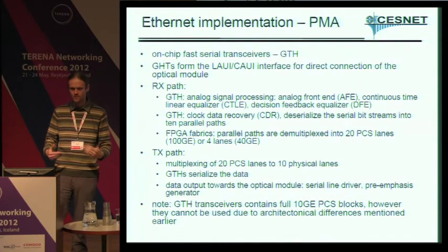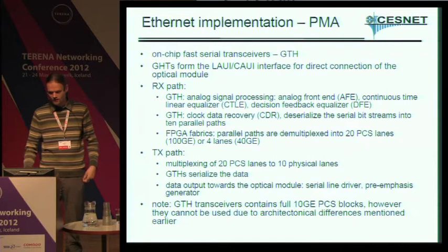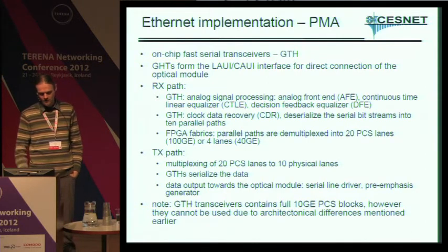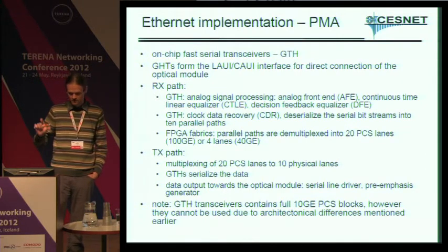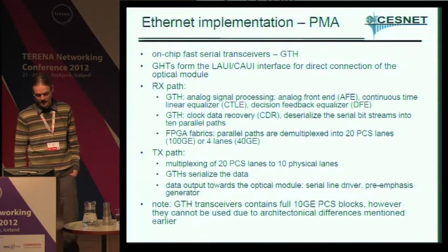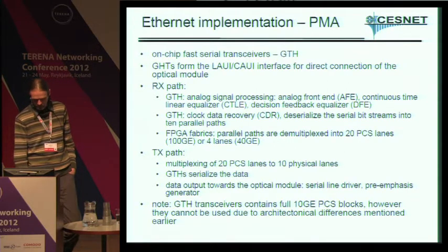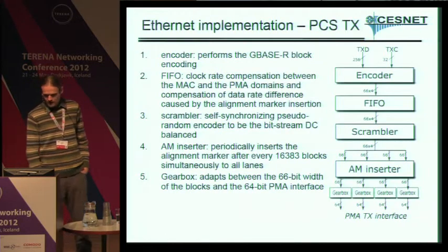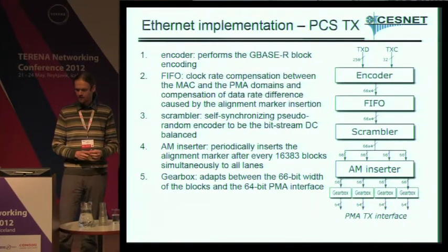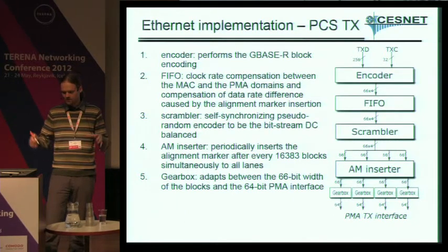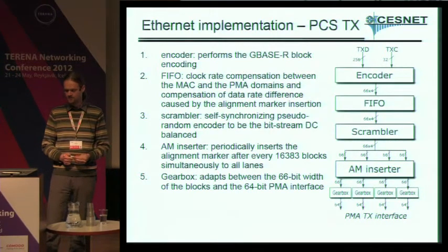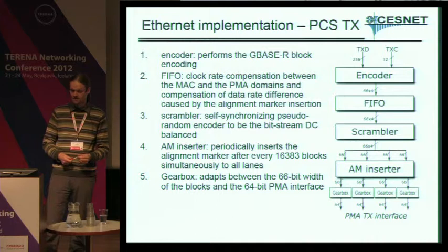So in our implementation, we will have to bypass all these beautiful blocks within the GTH that are available now. The PCS layer will have to be implemented completely in the logic by us.